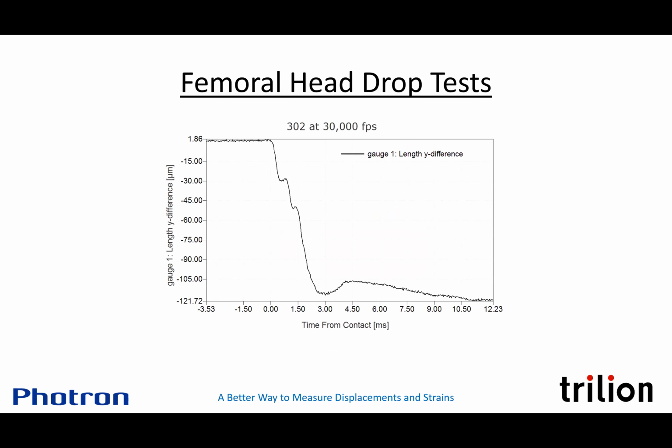Complicated 3D geometry, but the DIC can lock onto that. What we were seeing were these non-linearities in the insertion process. We sped up the cameras just by reducing the resolution. Nothing else needed to be changed in that setup. We cropped the field of view, went faster, and saw that these discontinuities were really, really occurring.